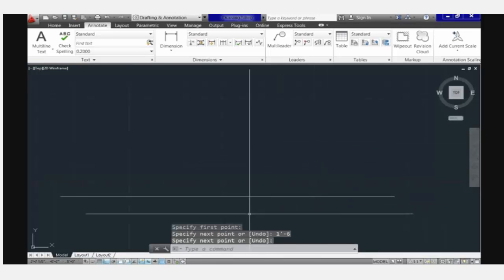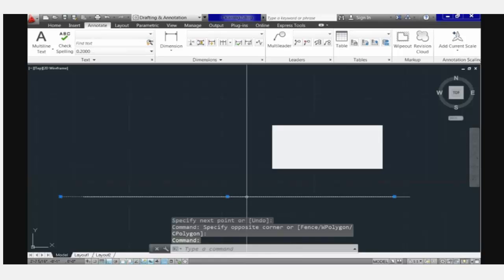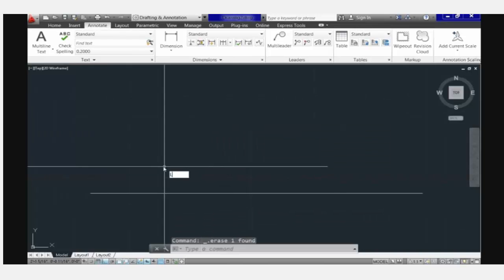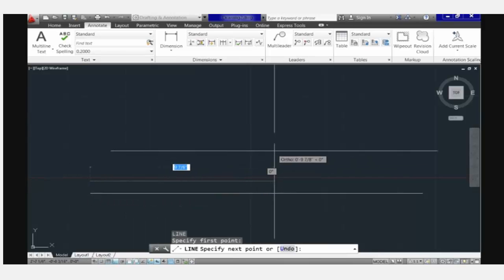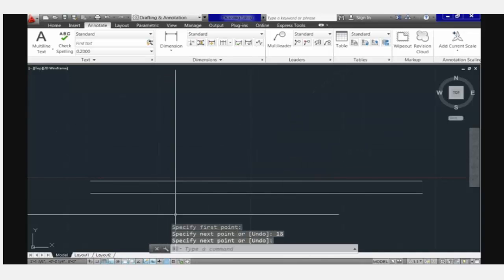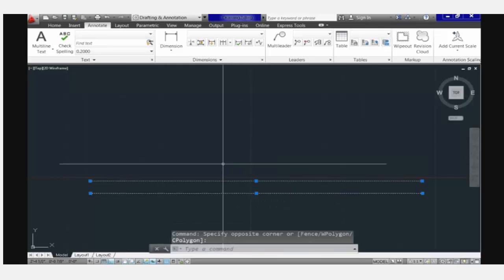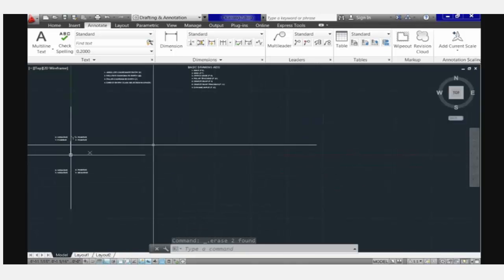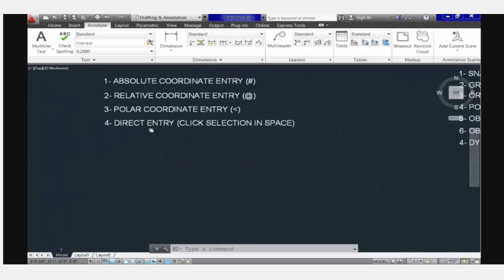If you're using architectural units, any number you enter in AutoCAD means by default inches. So you can get the same result by just using numbers. Instead of using 1 foot 6 inches, I'm going to use here 18 only, which means inches, by the way, and actually we're going to obtain the same result. Just take the precaution that when differentiating between a whole number and its fraction, or when specifying between feet and inches, you have to use the hyphen instead of the space bar.